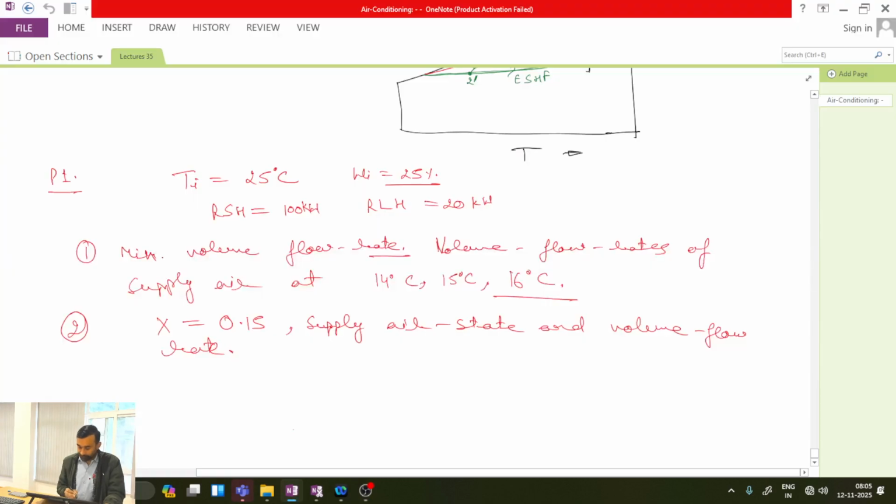Good morning. We have discussed different types of summer air conditioning systems in the previous class, and based on that, I gave you one numerical problem in which the indoor conditions were maintained at 25 degrees Celsius, and I have written it wrongly. It should be phi I, relative humidity, because it's in percentage. It is not the absolute value of humidity. The room sensible heat load was 100 kilowatt and the room latent heat load was 20 kilowatt.